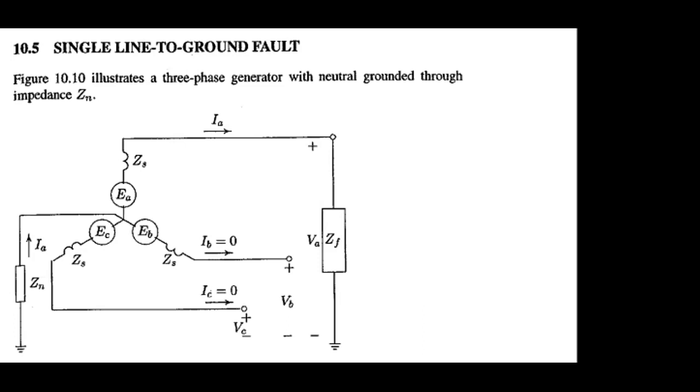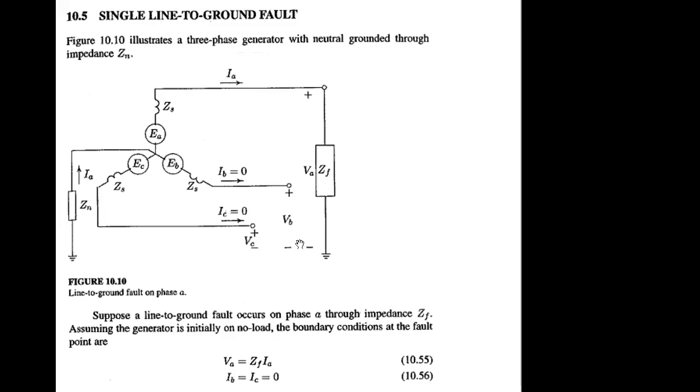Okay. First part is the single line to ground fault case. Actually, when do we consider that scenario, or what will be the outcome if we have single line to ground fault? Three different aspects you have to address. One is when you have the fault scenario, that fault will have some voltage, right?